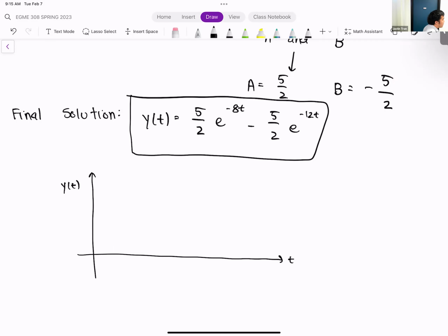When you run over a speed bump with your car, you would initially expect to have some discomfort. When you go over the speed bump, it produces an initial velocity and you kind of feel that in your car. You kind of hop up. Because of the initial velocity, you actually see that in the solution; it kind of goes up like this. So that's you going over the speed bump, and your car has a vertical displacement. But because of your shock absorbers, which in this case are in pretty good condition, that initial discomfort quickly goes away.